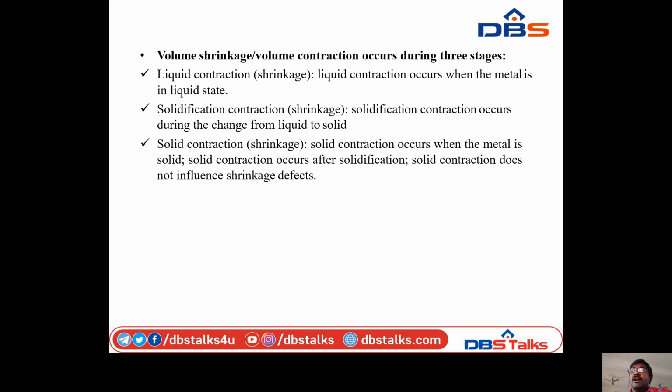Solidification contraction occurs during the change from liquid to solid. Solid contraction occurs when the metal is solid, after solidification. Solid contraction does not influence shrinkage defects.